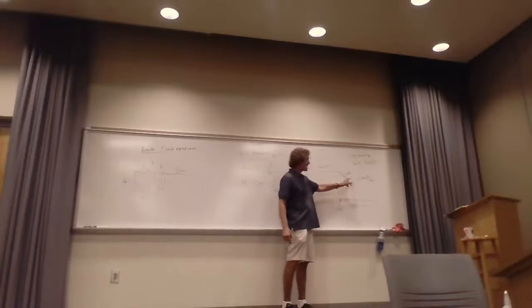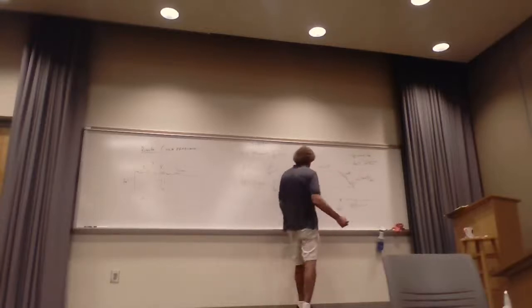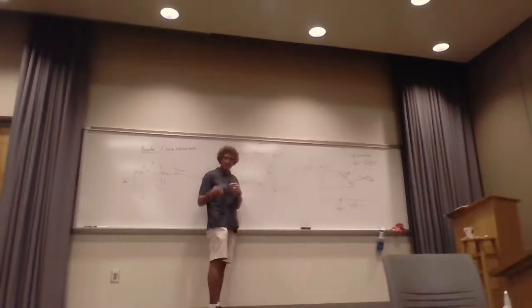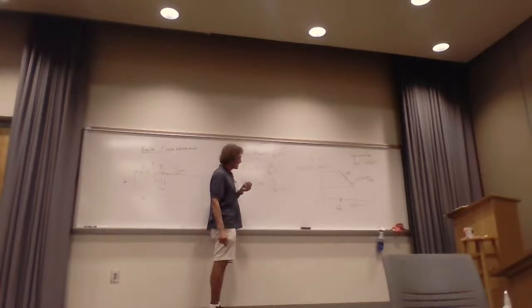So I can figure out how many decades or fractional decades I've gone, because I know the slope of that line to the absolute minimum. Or I can calculate the resonant frequency, take that resonant frequency and put it into this equation and then back it out that way. Y'all follow me? Because omega is 2 pi f. Agreed? So either way you'll get it, and I'll show you both ways, but I want to get through this part of it.